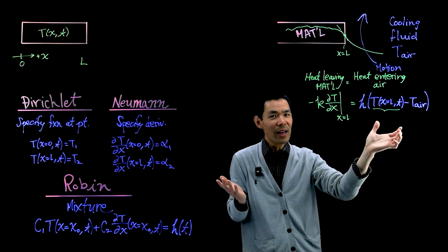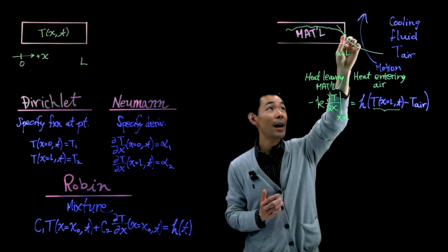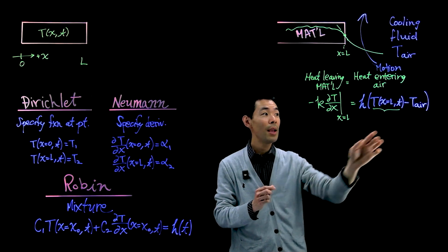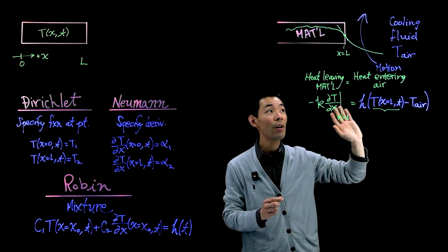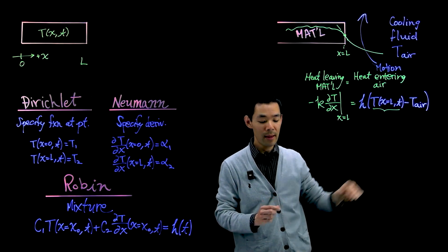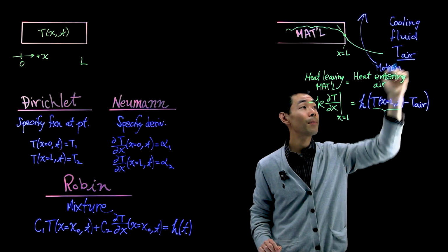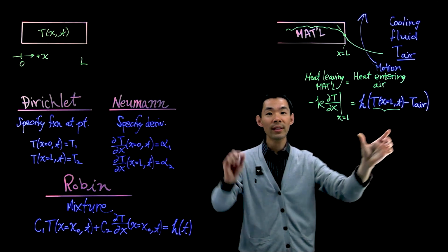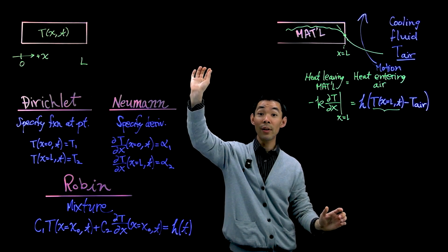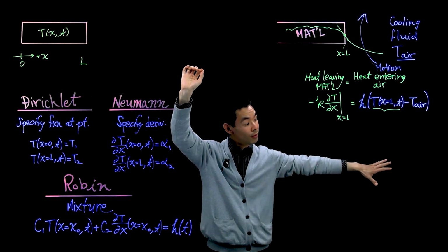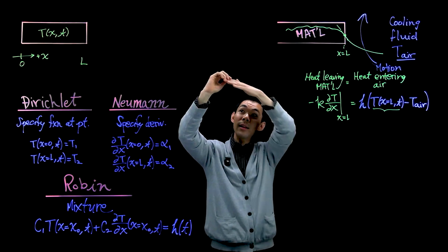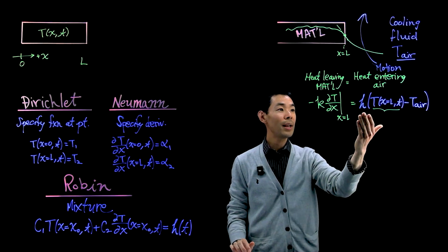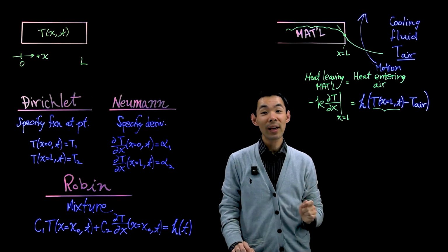So it's whatever temperature is at x equal to L, that point at the interface of the material contacting the surrounding fluid, minus the temperature of the air very, very, very far away. That's this temperature out here in the air very far away. So it's the difference in the hot surface of the material of your GPU and the coolant temperature very, very far away. That difference in delta T is multiplied against h, which is called the heat transfer coefficient.